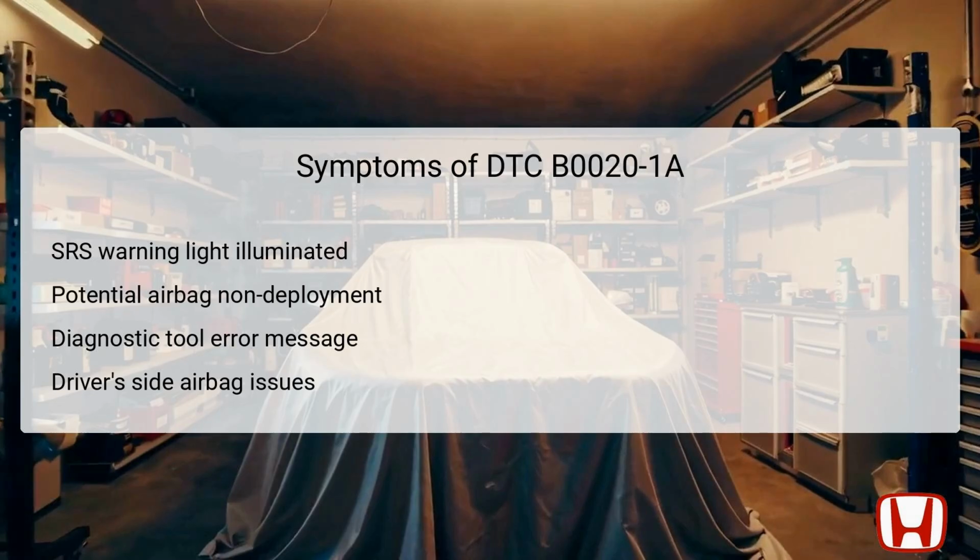Additionally, if you connect a diagnostic tool, it is likely to display the error message associated with DTC B0020-1A. Furthermore, discrepancies in the driver's side airbag functionality may also be noticed, potentially highlighting a mechanical failure or disconnection in the airbag or its components.